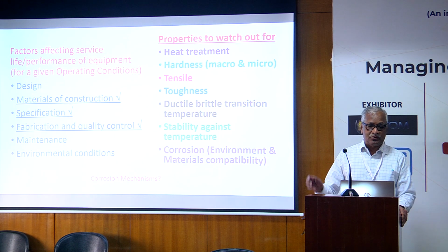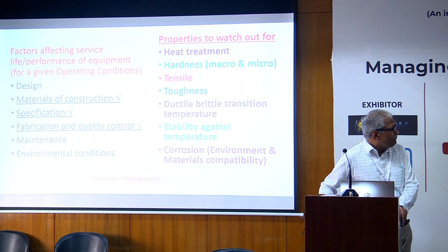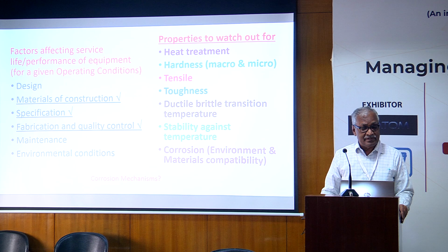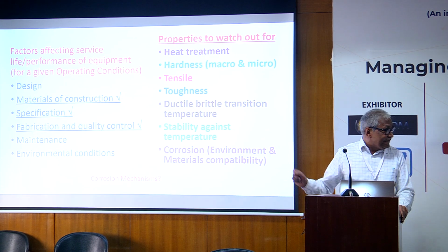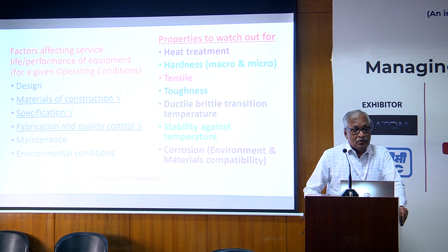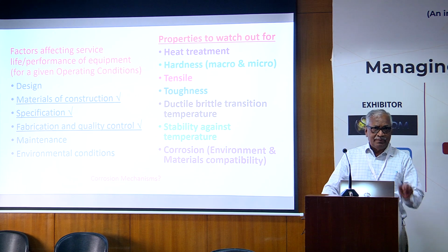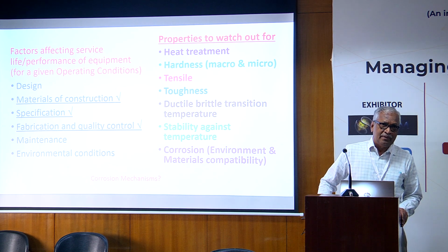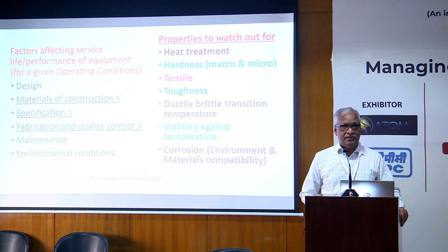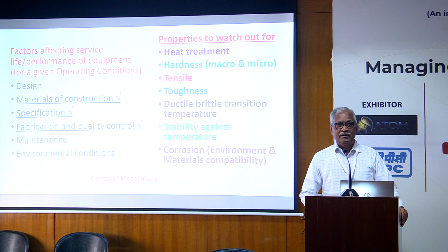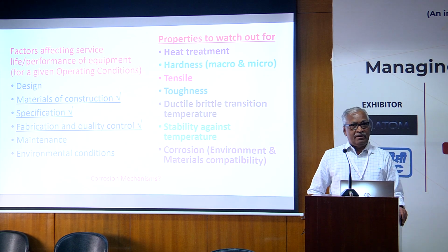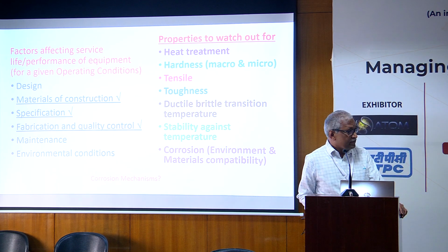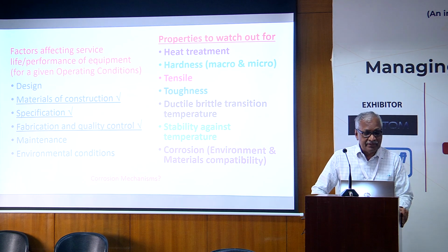And again, I told you concepts. Generally speaking, some of the factors affecting corrosion performance in real life situations are listed here, and what I ticked are related to material science. We look at materials of construction, which is simply two words. But if you go into details, if you look at some of the NACE standards, they give very gross specifications, 304L, 316L, and so on. But then you dig deeper into it, and we have issues there. The codes are never given to the finer points of that. So that's the reason why I need to know more about the materials.